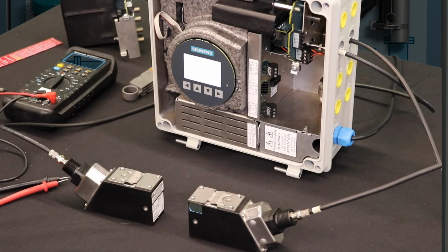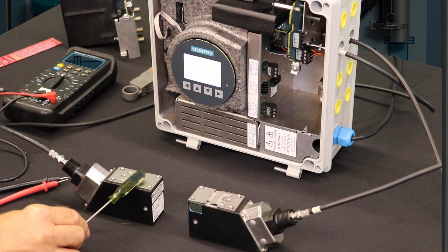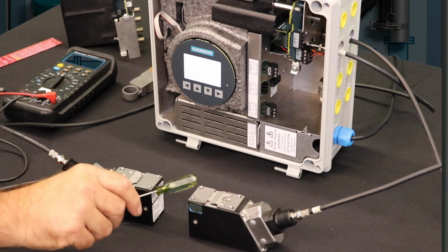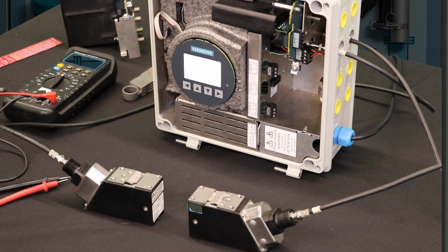And another possibility for liquid measurements only, if the sensors happen to be mounted on the pipe in reflect, what you can use is the half pipe diameter, program that in and switch to direct mount. And you can also check for the received signal. So as an example, if these two sensors were mounted on a pipe which was 4 inches in diameter, what you would do is reprogram the meter at 2 inches in diameter and switch from reflect to direct, 1 traverse, and then look for the signal.